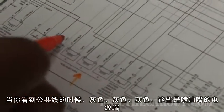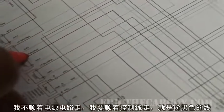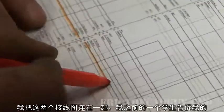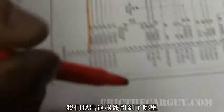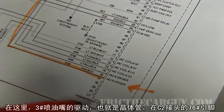You got it. Okay. So I'm going after the number 3 injector, and one of the things I look at initially is when you see a common wire. I see gray, gray, gray, and gray. Those are going to be your power feeds for the injector, so I'm not going to follow the power feed circuit. I'm going to follow the control wire, which is a pink and black wire. I put these diagrams together before, and I actually had one of my students help me. Thank you, Josh. We map out where it goes, and it says right there injector 3 driver, which is a transistor, and that's what controls that fuel injector. That is on pin 76 on the C2 connector.